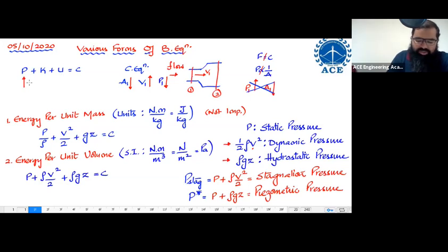The answer to that question is, if kinetic energy were increasing, the question should say the discharge is changing. If I'm changing this pipe into this pipe condition, and nothing else is mentioned, I would assume the discharge initially and later are the same. Remember this: something regarding discharge should be mentioned for me to talk about kinetic energy. Otherwise, we always assume only pressure is increasing. Pressure takes the headache of changes every time.